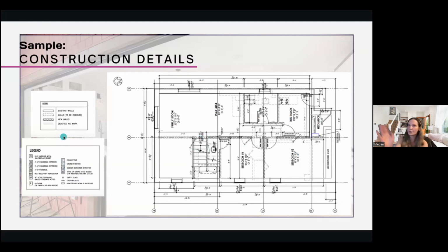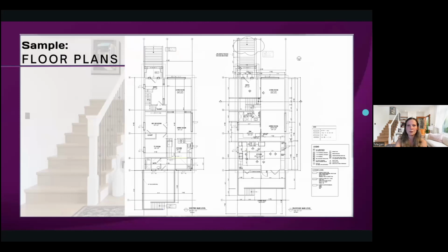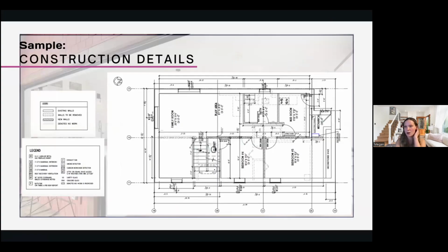Now, as we've been going through, you may have noticed that all the drawings have what we call grid lines on them. This one's kind of set on its side, but you'll notice that it's got 1, 2, 3, 4, A, B, C, D, E. And so those are always in the same place on each drawing that you see. So if I back up to a floor plan, it's the same intersection on each drawing, between the floor plans and wherever they show up on any given drawing.